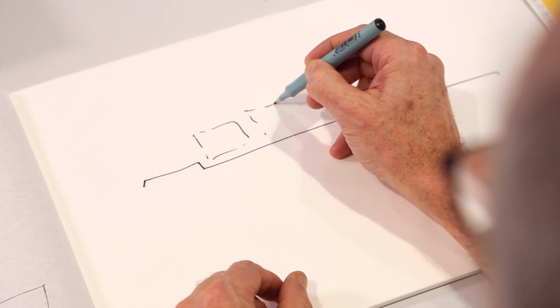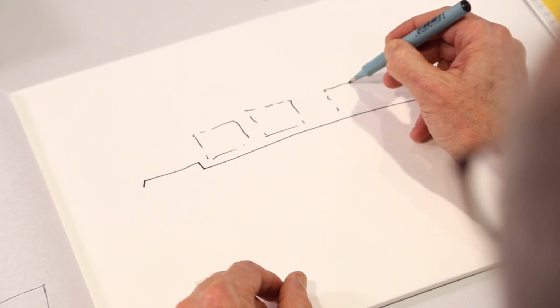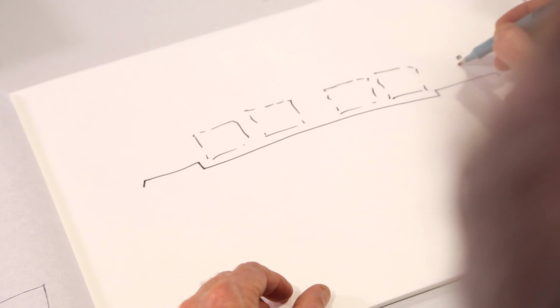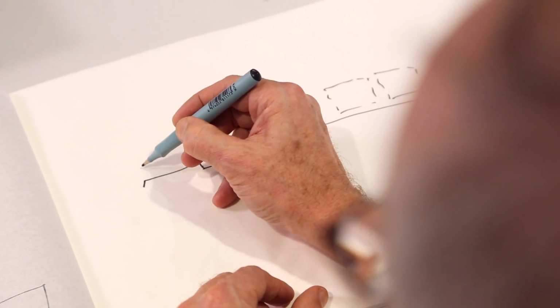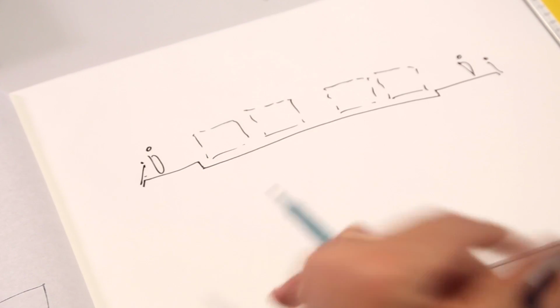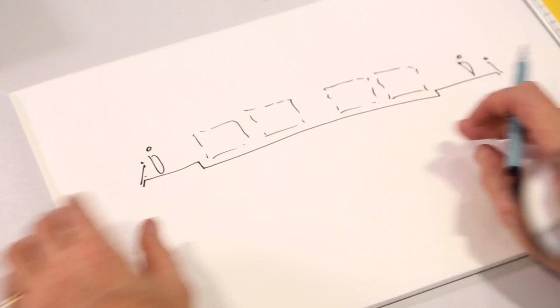Maybe there's a cycleway. And so that's your functional cross-section, which defines the width of the bridge. And you can begin to put a bit of scale on this. What does a person look like on that scale? Before I even actually start thinking, okay, how am I going to support that surface? And you need to be thinking about both of those at the same time.